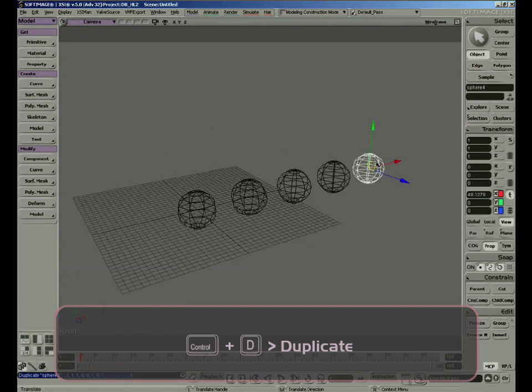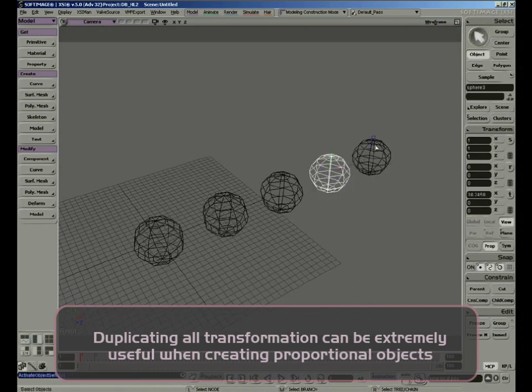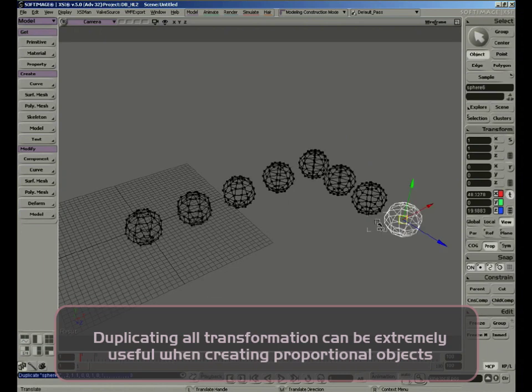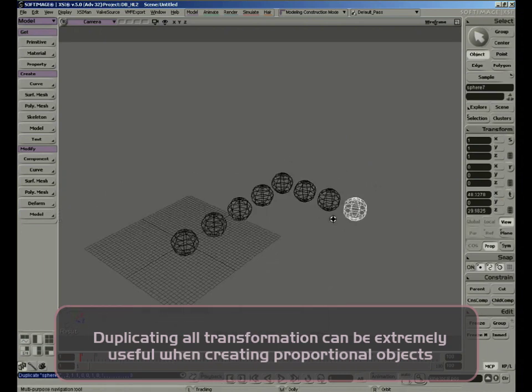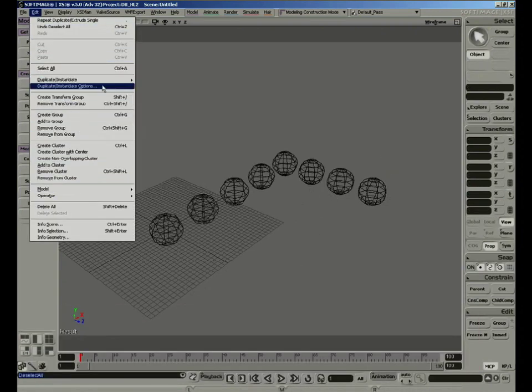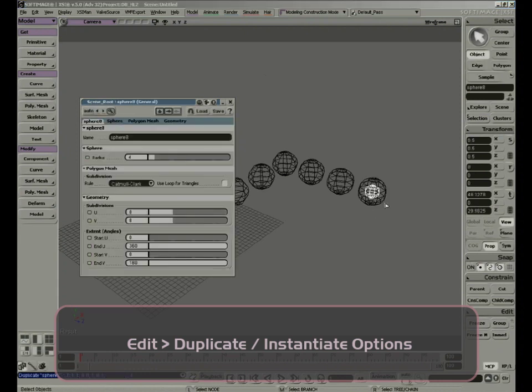If, for example, we want to duplicate this sphere, but we also want to duplicate the movement to the front, we do the following. Just select another object, and then reselect the object we want. Now duplicate and move. This way the operator history is related, and we continue to duplicate the other objects. Control D, Control D. If we want to stop working with the options, go back to our D, duplicate options, transform, and here we have the operators that are being memorized. If I want to affect the scale, 0.5, 0.5, 0.5, when I duplicate, I will get those values.